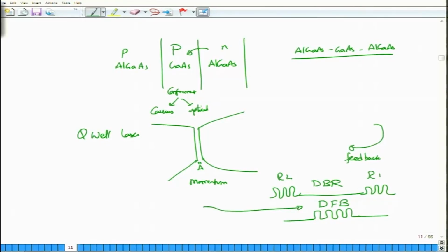Most practical lasers that we use today are DFB quantum well lasers, and these provide of course both wavelength selectivity, and wavelength selectivity is important, and feedback. Wavelength selectivity is important because, as you know, the radiation spectrum of a laser or of a semiconductor material is quite wide, but by incorporating the feedback in the form of a DFB or a DBR laser, it is possible to have an extremely narrow line width laser that can come out of this one. Okay. So, this is what you would actually have in the output when you put a wavelength selective feedback mechanism into the system.